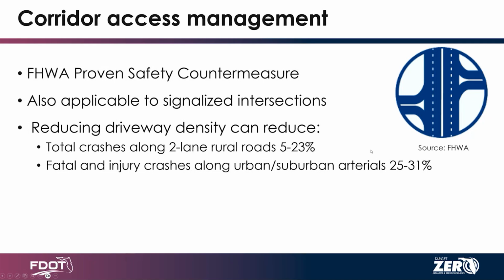I just had two thoughts. One was the question of what is driveway density, but it sounds like it's just fewer driveways, like in locations. And for driveway density, it's just the frequency of driveways. So maybe you have 100 driveways per mile, and if they're all open access driveways, can there be any consolidation to reduce that on a corridor where there's challenges, to a lower frequency, to reduce those number of conflicts?